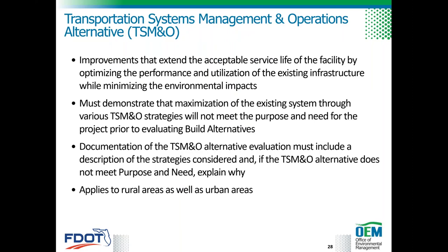The TSM&O alternative provides operational improvements that extend the service life of the facility while minimizing the environmental impacts. The TSM&O alternative may include upgrades or additions to the existing facility, such as ramp signals, work zone traffic management, road weather management, congestion pricing, among others.